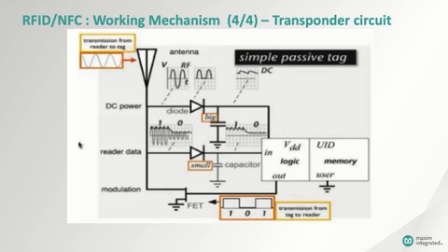All right, now we're ready to take apart a typical tag and see what's in there. Everything starts with the antenna, and that's often in the form of a printed coil. In the case of a passive tag, there's a circuit that rectifies and filters the received signal to harvest enough energy to run the electronics in the tag. Now, in parallel, another diode capacitor circuit acts as an AM demodulator that extracts the data from the carrier. The data can be instructions, measurements, new status information that needs to be stored in the integrated memory. It could be anything. The tag can also be interrogated for stored information.